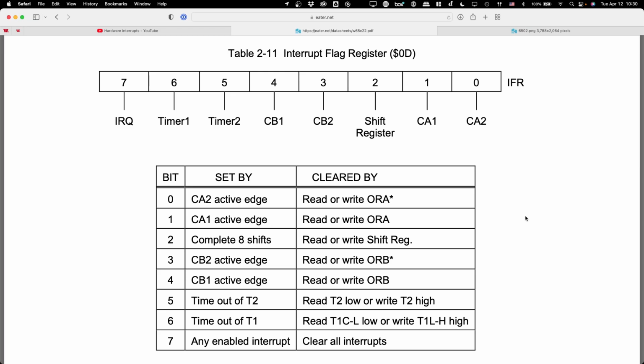So when I hit the button, I've got 5 buttons, and maybe some of them are being pressed and others aren't. An interrupt gets triggered, and it's going to latch, okay, these ones were pressed and these ones weren't. And then when I read from this register, I can say, oh, well, the bit pattern in this register is blah.